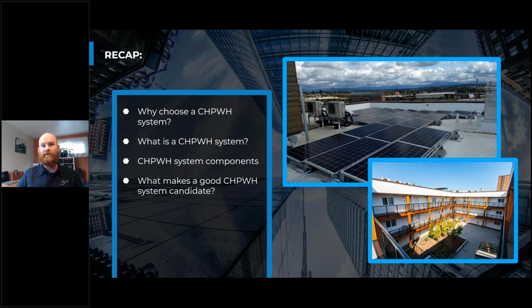And those components are a primary heat pump water heater, a primary storage tank, or somewhere to store that hot water, a temperature maintenance system, which might be integrated with our primary tanks, or it might be a dedicated temperature maintenance heater and heating system, and then a control system, some way to control those components, whether it be just the heat pumps or multiple accessory components to that domestic hot water system.